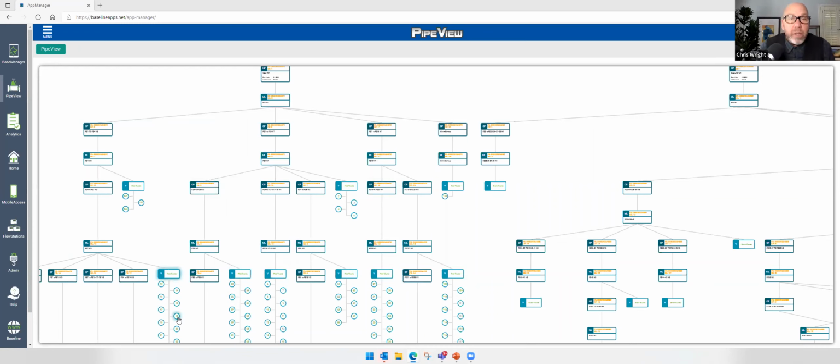So that's one of the powerful functions of the flow station technology that we're going to speak to in the next live Tech Talk Tuesday, is we can group control points together so that if we have a normally closed control point, i.e. a normally closed master valve anywhere in this hydraulic structure, we know that if this zone is calling for water, it needs to open this control point as well as opening the primary control point in order for water to flow and get there.